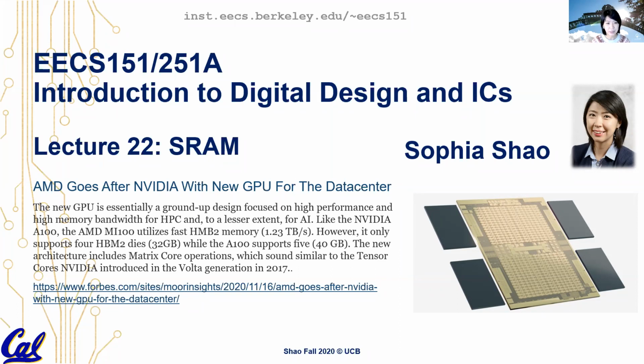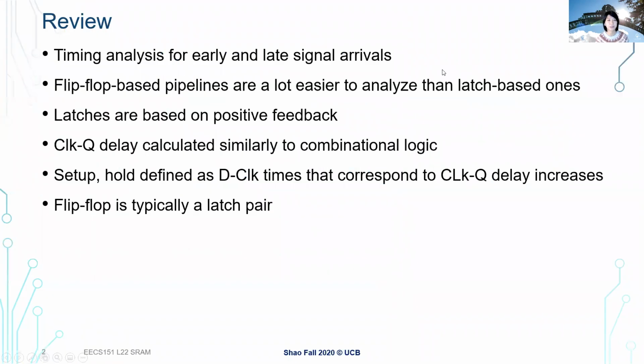So with that, let's transition to our third module, thinking about sequential elements. We talked about flip-flops and latches before as a way to store or track state. A very important part is also the different delay components. You'll notice the delay discussion started from combinational logic in the second module, where we discussed CMOS logic and how you can turn CMOS logic, both the gates and the wires, into an RC network to calculate the delays.